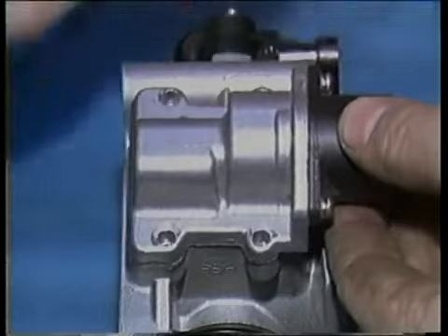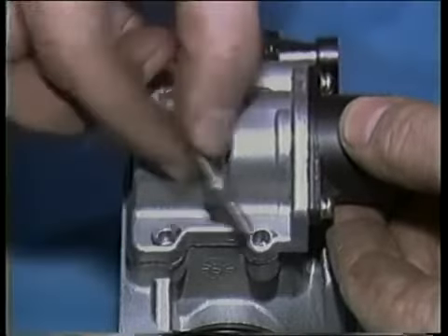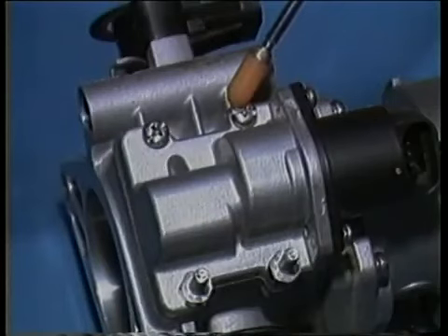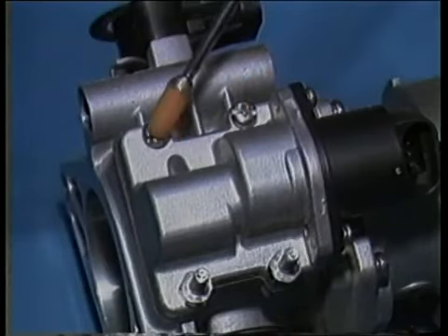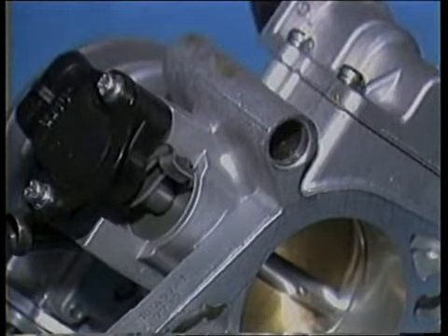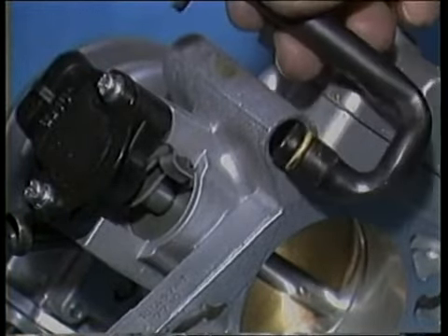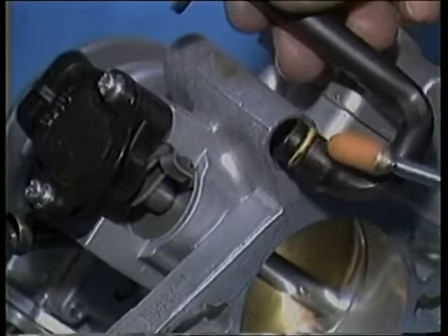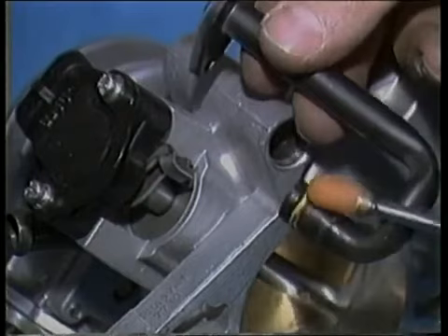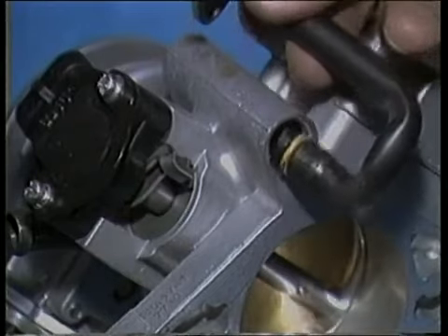When tightening down the throttle body housings, or a large unit like this idle air solenoid, tighten the screws in a crisscross pattern to provide an even clamping action across the sealing surfaces. Replace any vacuum seals with new ones. After making any needed repairs, reinstall the throttle body in reverse order of removal.